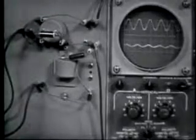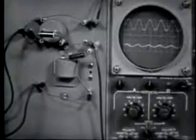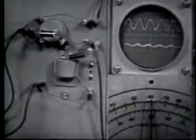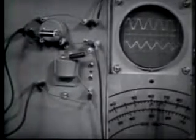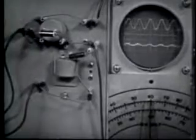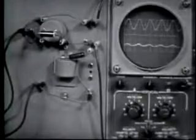Now we've said that the T and pi section filters provide improved filtering action over the simple L section. What do we mean by improved filtering action? Just this. This L section band reject filter rejects a band of frequencies from about 500 hertz up to about 700 hertz. Now since the specific frequency we want to reject is 600 hertz, this circuit is not too precise, is it?